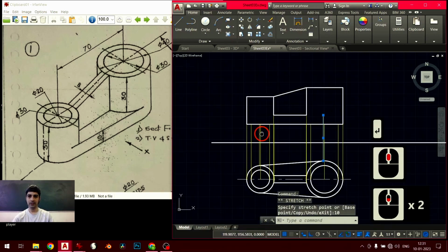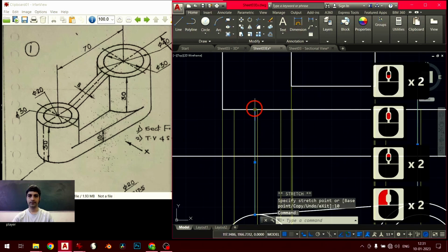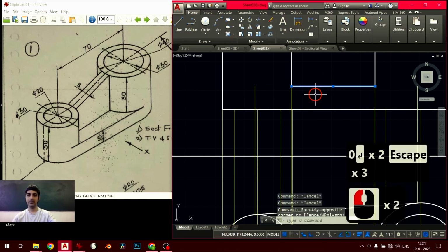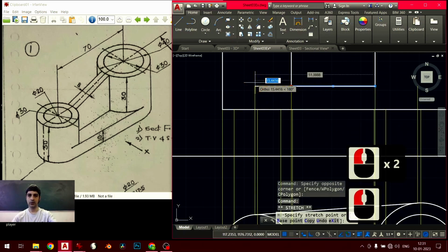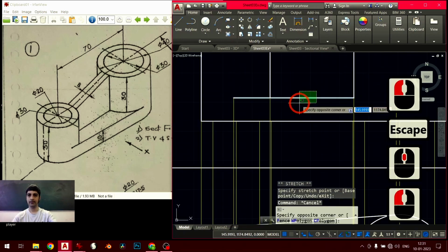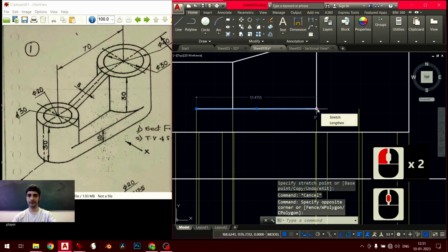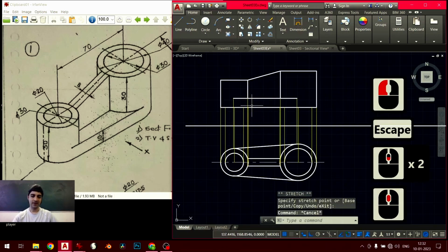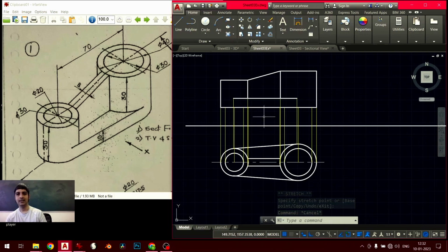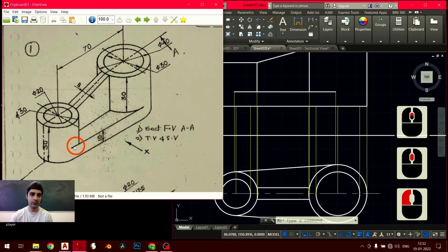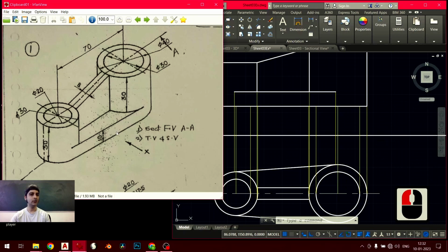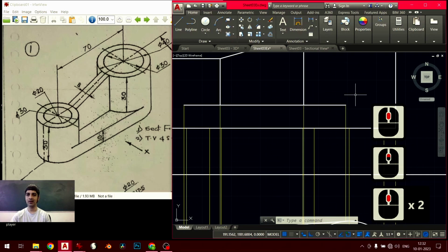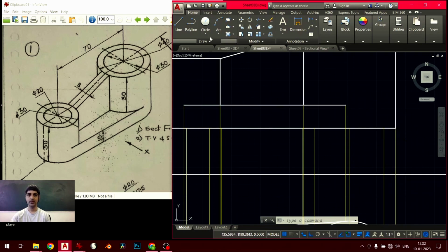And I'll do the same here as well. It should be this projector, 10 units. And then I can just stretch this end out all the way to go inside there. And the same thing on the other end as well. We are still not done. The next thing we need to look at is how to represent these kind of edges, which end in curves. So for that, you're supposed to make a small arc turned upwards on both ends, for which I can use